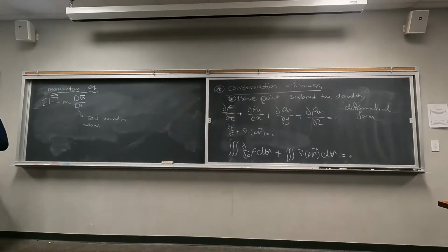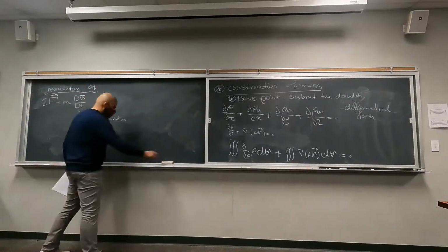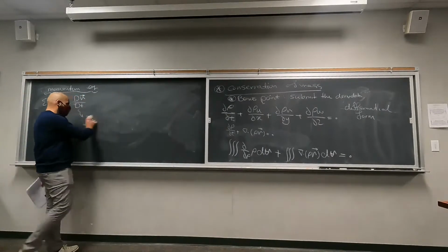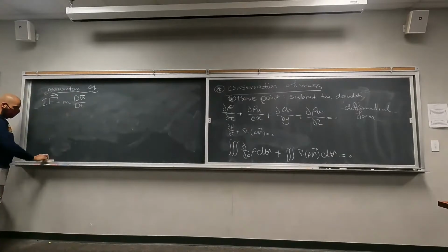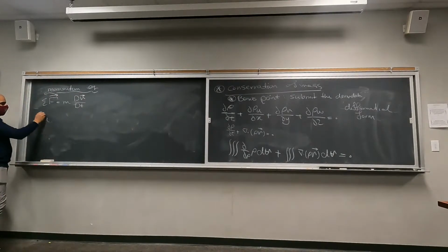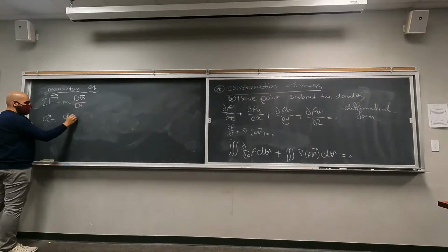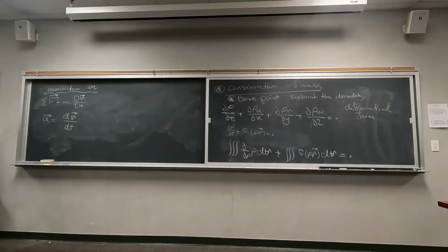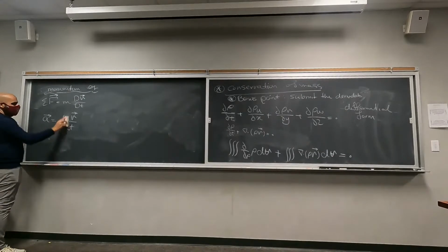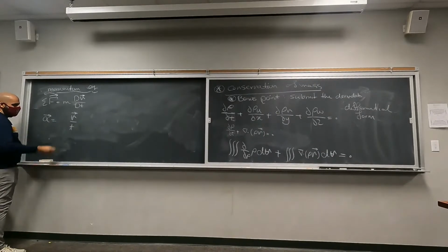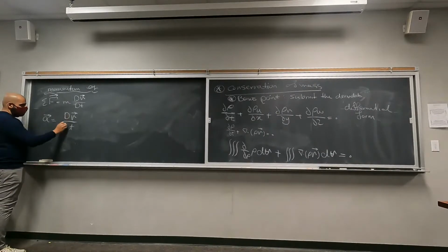No. Okay, so we have to talk about material derivative. I assume up until this point, you have always calculated acceleration as the regular derivative of velocity versus time, right? But what I'm saying is that this is not a regular derivative, the acceleration. Acceleration is actually a different form of derivative called a total derivative.